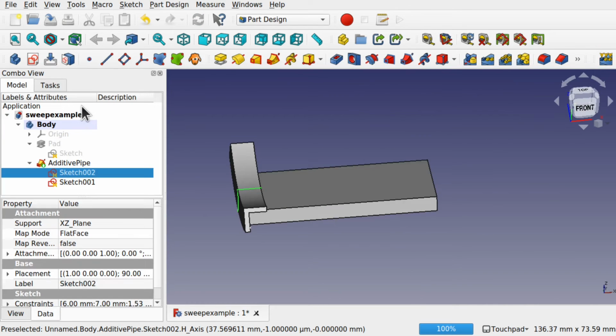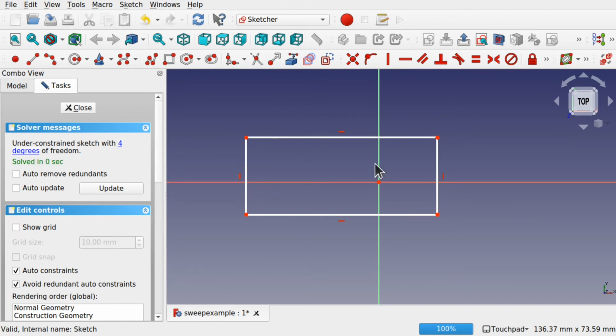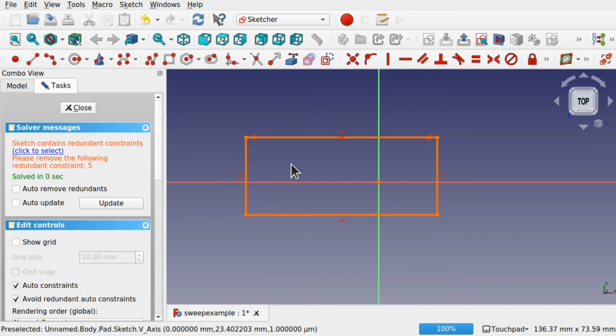Let's close this. And because this is attached to here, what we can do is come into the pad, double click it, and we need to move this across because when we reflect the item, it sits disconnected from this body. So all we have to do is take these 2 points and this vertical line and place this in symmetry.